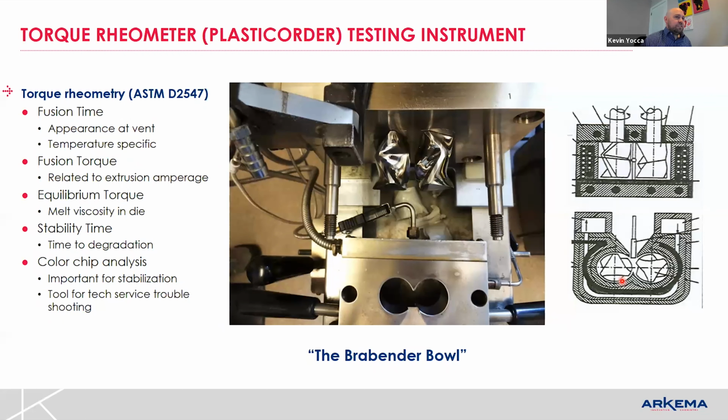You're taking a small section, doing some mixing and trying to predict essentially how your PVC compound will act, fuse, how stable it can be, how much torque it can generate when you modify it with different additives, even how much degradation you can see in real time. And it's a very simple tool. You know, I always tell people it's a dumb tool. It's going to turn on, it's going to work as hard as you tell it to, get to the temperature you tell it to, and what you take away from it and how you modify your formulation is totally up to you. But it's going to do its job. It's going to turn the paddles, and it's going to tell you how hard it is to turn.